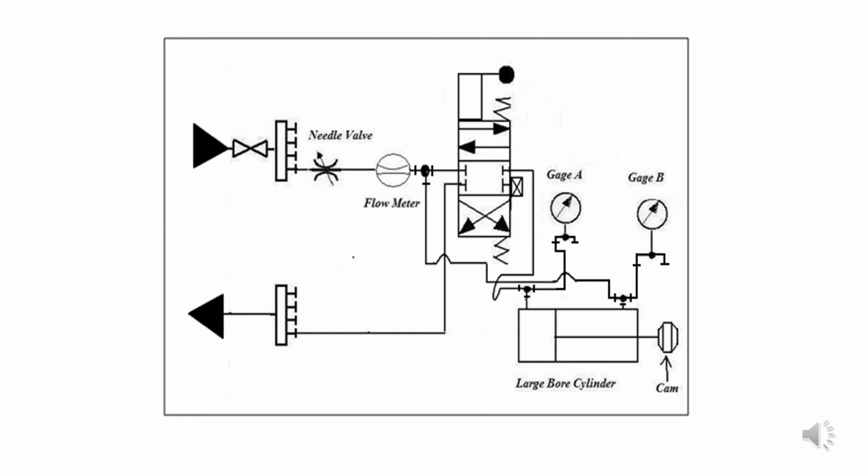Now, the reason for the needle valve is because the flow coming from the pump will actually impede the oil entering the DCV, so we have to slow that flow down to be able to see the full effect of the speed increase during extension. Normally, a circuit like this would not use a cylinder like we have. The cylinders that they use in these types of circuits are normally 2-to-1, meaning that the area of the piston is exactly twice the area of the rod.